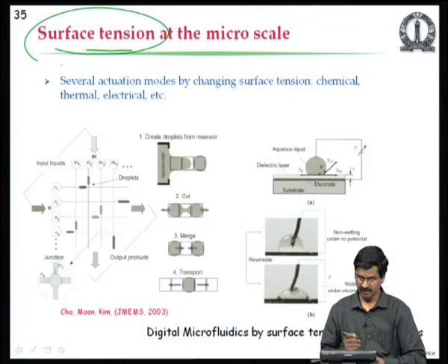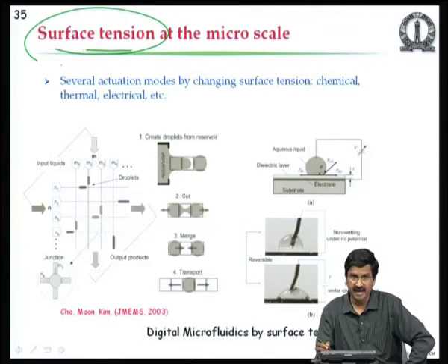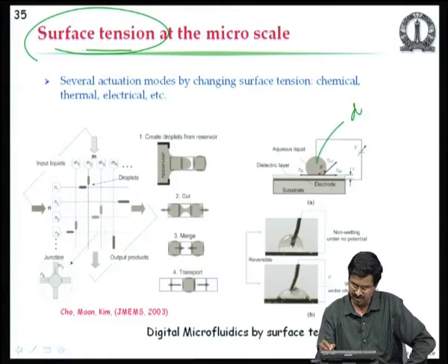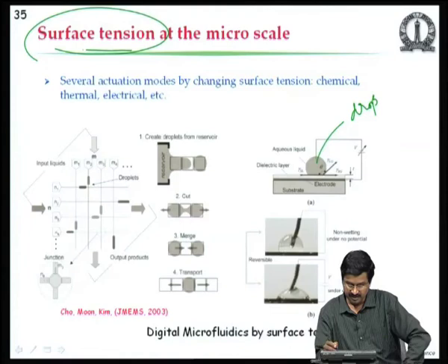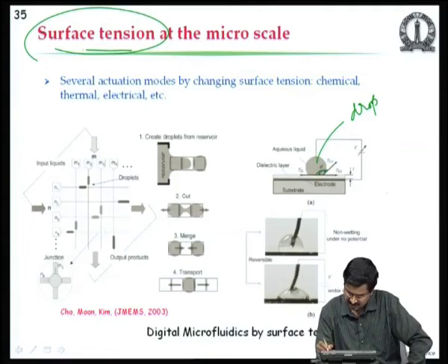And here we need to talk about the contact angle. So, if I take a substrate and put a drop, this is just a drop of a liquid of some kind, it could be even water. The contact angle is this angle, so if I have the surface and the drop is like that, only mercury on a normal surface will be like this, but even water can be like this on a hydrophobic surface.